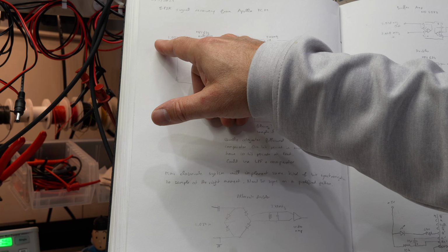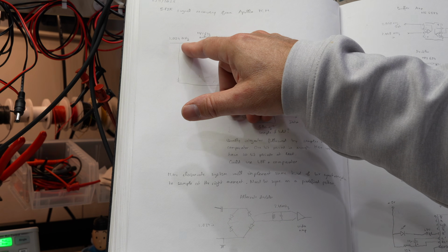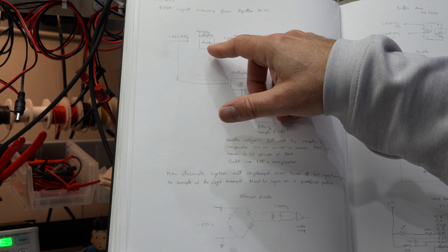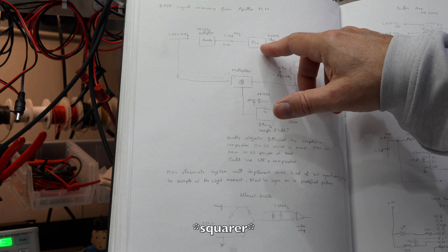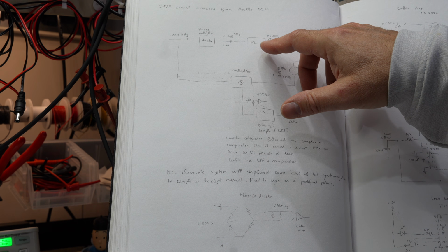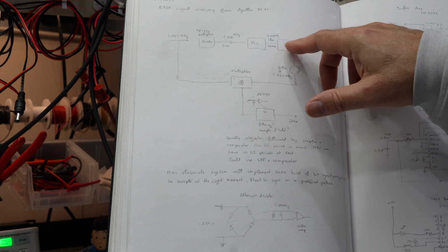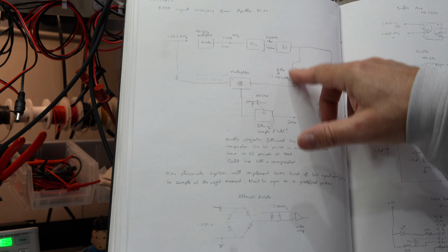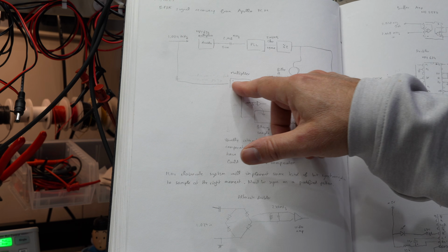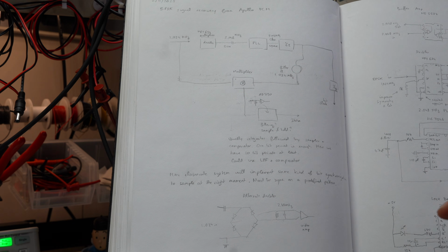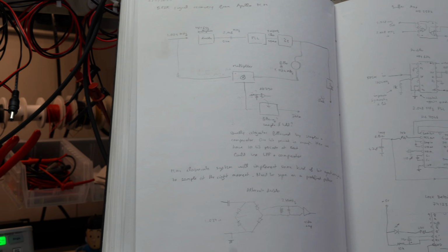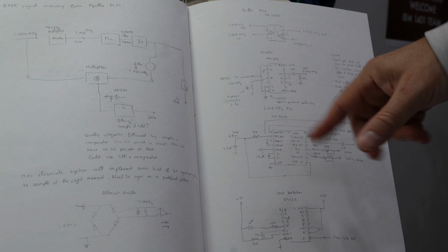But basically you get your BPSK at 1.024 MHz, and then the first thing that you need to do is recover the carrier, and for that you use a doubler, then you use a PLL loop to sync on it, then you divide it by 2. Once you have the carrier, you multiply it by the BPSK signal, and you'll recover your bits after some filtering. And it's all made by a series of little circuits I have detailed here.